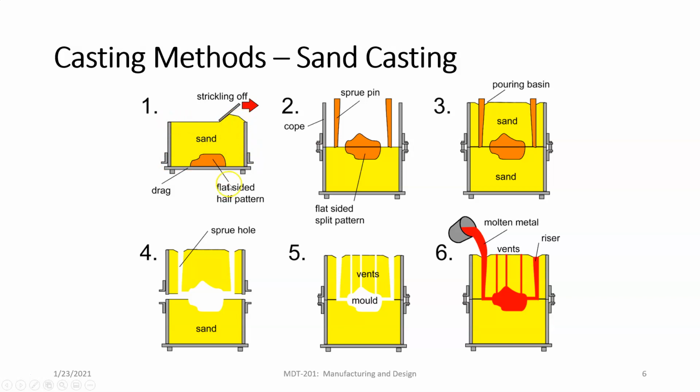And you pack it in there really good. So the sand is around this half pattern, right? And then you level it off, okay? Remember, the sand is going to stick together, right? And then you flip the drag over. So now the drag is in its proper location, right? You flipped it upside down here.